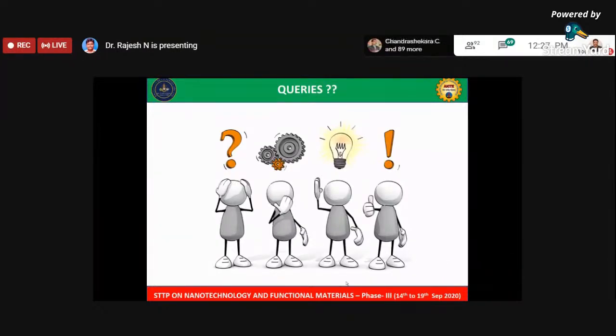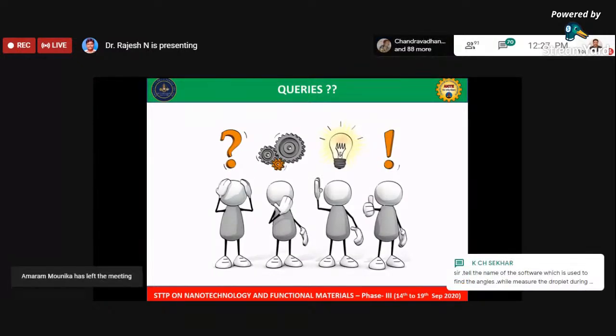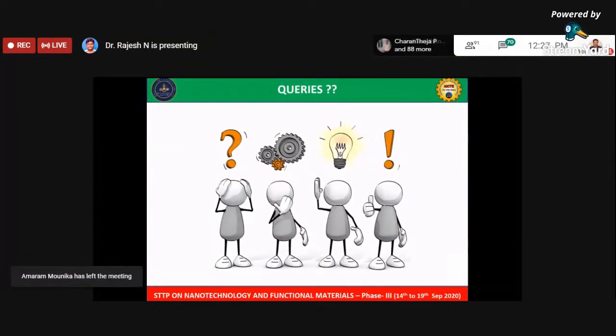I think one more question is there, whether work hardenability in machining of superalloys is still a challenge in the industry. Yes, it is a challenge. How best can we address this issue? One way out is basically to reduce the forces and reduce the cutting temperature. If you can reduce the forces and the cutting temperature, then this work hardenability can be minimized to a certain extent.